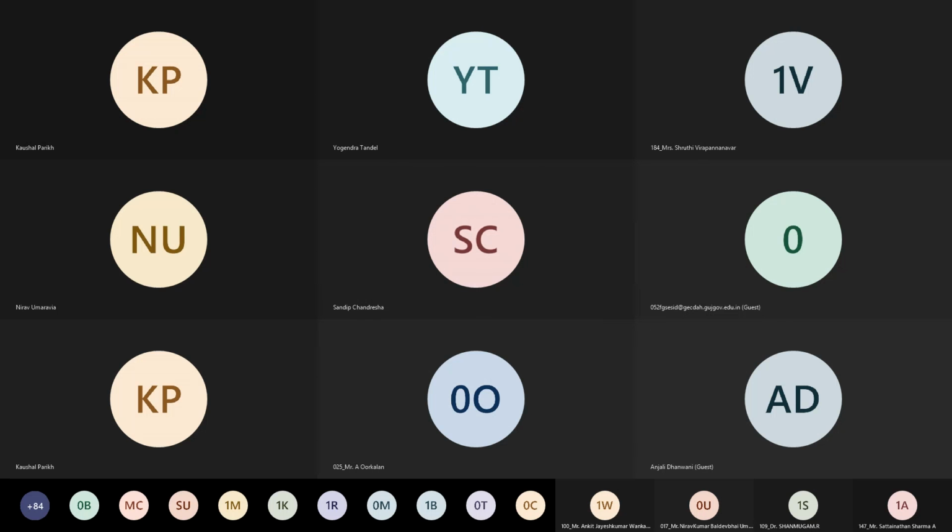I can give the example of the damage types. Damage type 1, 2, 3, 4, and 5 have been enlisted in this local region. During the visual inspection and certain NDT tests, if they find it is under criterion number 5, then instead of carrying out any kind of retrofitting technique, you have to demolish the structure and carry out reconstruction.